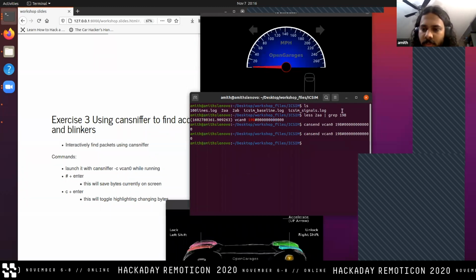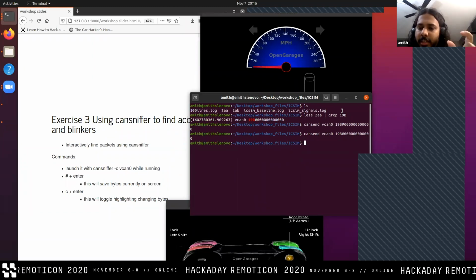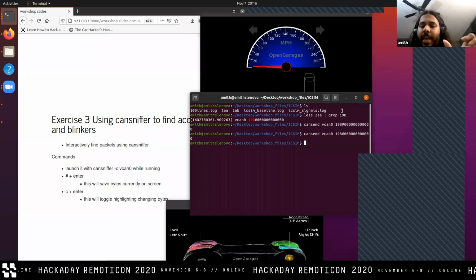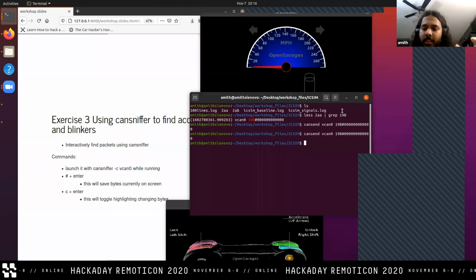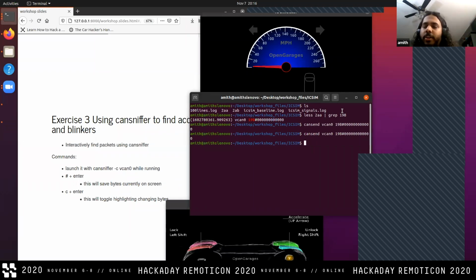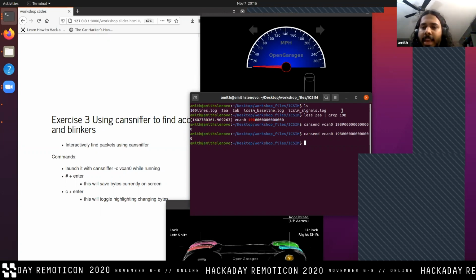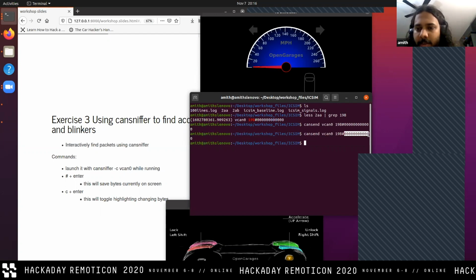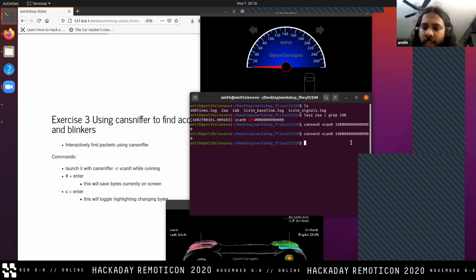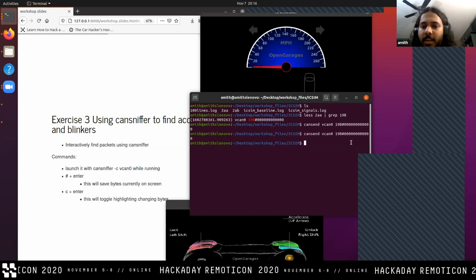Stephen, 19B is the arbitration ID. So remember, each CAN message has an arbitration ID, which tells the system what node of the network it's coming from, followed by the actual data packets. So 19B is the actual module, I don't know if the virtual module, that sends the command.